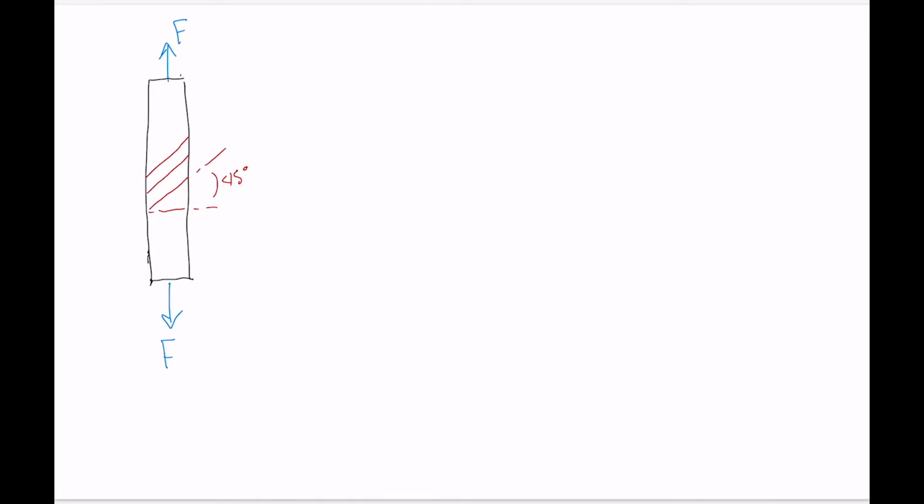And what's going on here is after the material reaches its yield point and starts plastically deforming, within the atomic lattice work of the metal, dislocations are forming, where you've got rows of atoms that are being split and joined up with other atoms. And as those dislocations pile up, they create these slip planes that are visible on the surface of the metal.